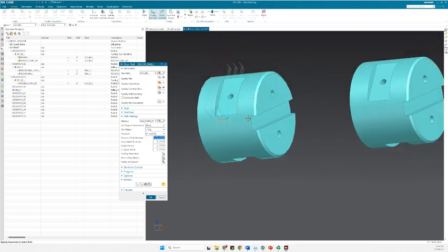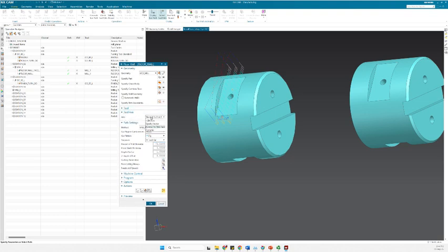And that is how we need to define that the tool axis would be perpendicular or normal to this surface of the floor. So for that one, we can go to the tool axis, and it's already in normal to first floor, or you can specify a vector, for example, and from the specified vector, then you can also define where it would be. But I put it now to the normal to the first one since it's already fine, but this is just to show you in case it won't be.